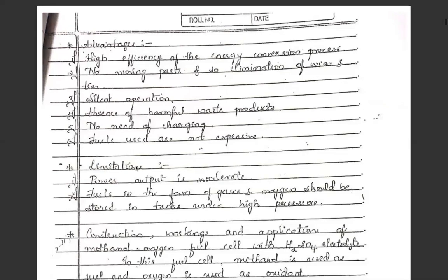And there are limitations. So power output observed from fuel cells is moderate. It is like 1.2 volt or 1.3 volt compared to batteries. Say, for example, a lithium ion battery will give us 4.5 volt. So compared to batteries, fuel cell output is a little bit less. But we can sort this out. How? A single cell will give us less output. We'll connect multiple cells, stack cells together in series. Then we can increase the power output. So this we can overcome by stacking many cells together in series. A single cell definitely has less power output.